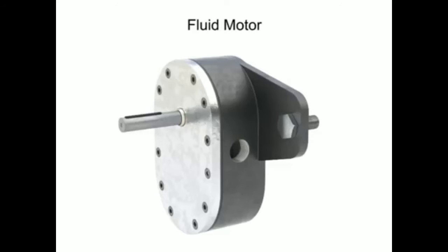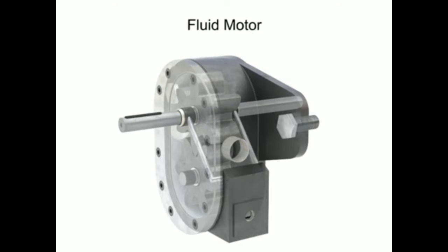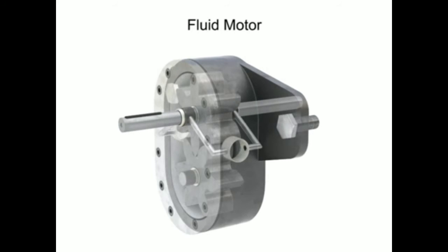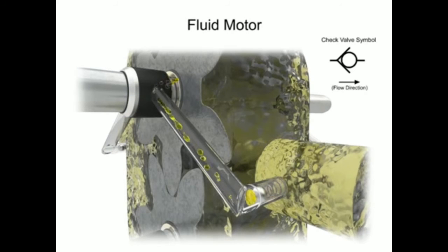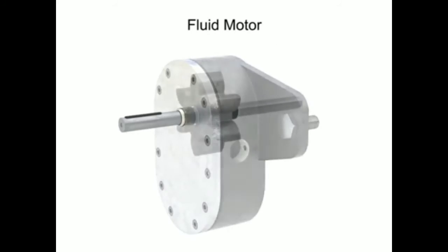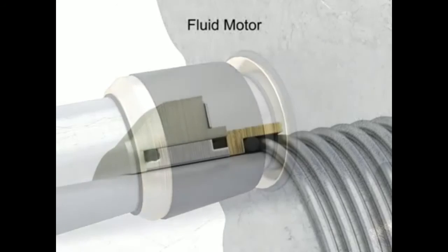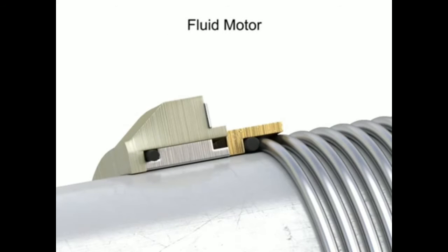The first method creates an external case or housing drain. The seal and bearing cavities are internally joined and vented through a drain port. Another method to prevent fluid buildup uses internal check valves. These valves allow accumulated leakage to flow in a specific direction to either main port, but will prevent backflow of high pressure into the bearing and seal pockets around the shaft. Finally, high-pressure shaft seals are utilized to minimize the consequences of high-pressure fluid exposure.